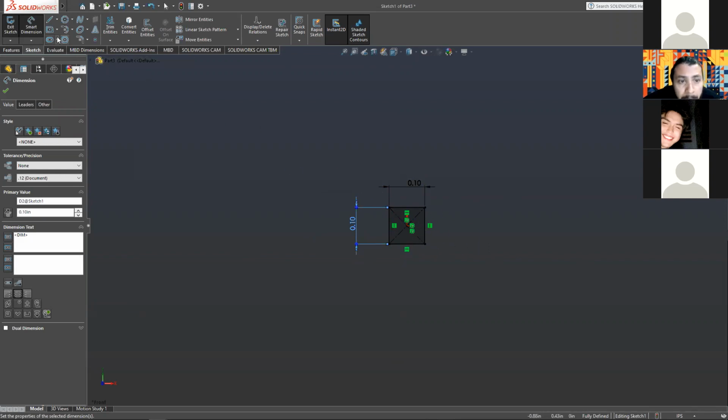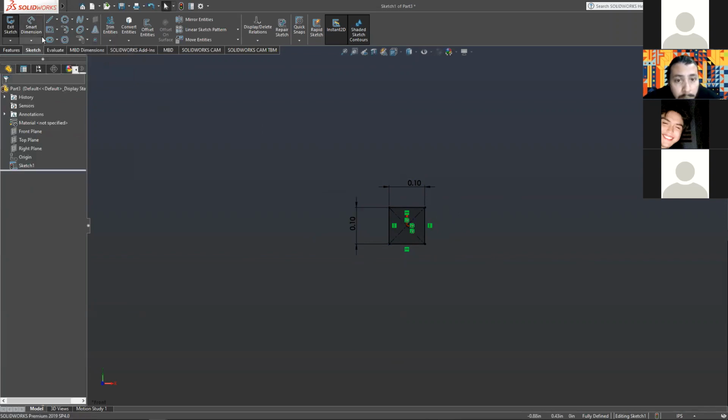Yes. Okay. These little icons will change depending on whatever you selected last. Since we've been using center rectangle, you can just click on the icon. You don't have to click on the drop down arrow all the time, and it'll be a center rectangle. Oh, bam, there it is. 1/10 of an inch.